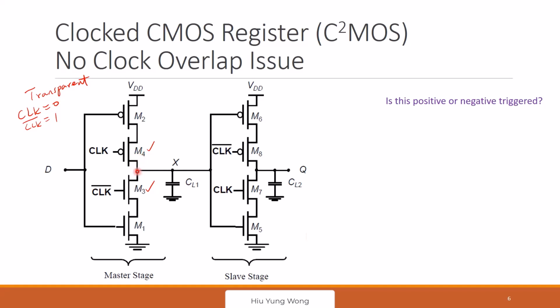When you analyze a circuit, you see something very complicated. What you will do is, you're talking about a certain clock value. When this is low, meaning it's high, this is low, then these are just lines. You just connect them with lines. Yes, they have resistor, they have capacitor, but they don't affect the function. We are not testing you on the delay at this moment, only the function, right? If they are lines, this is just an inverter.